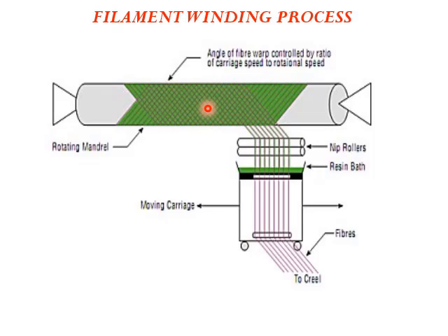Normally, once the fibers are wound on the mantle, the mantle is detached from the attachment and shifted to a furnace, where the curing of this material takes place. Once the curing is done, the material is detached from the mantle, and we get the final product in the form of pipes or tanks.